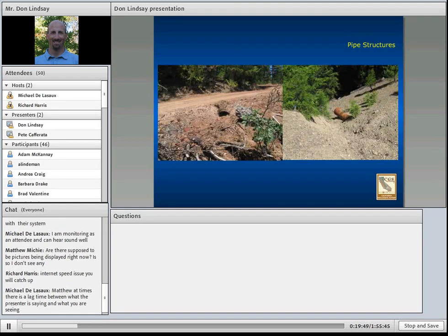Here are two cross-drain outlets. Note how they are installed. The one on the left was installed at a grade nearly flat. Thus, it is partially clogged with debris. It is good to install the cross-drain pipes with at least 2% more gradient than the grade of the ditch above to avoid plugging.